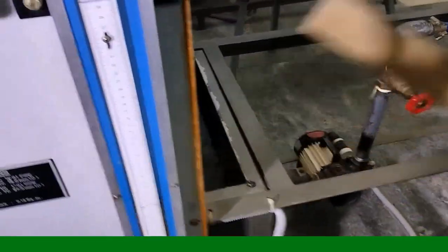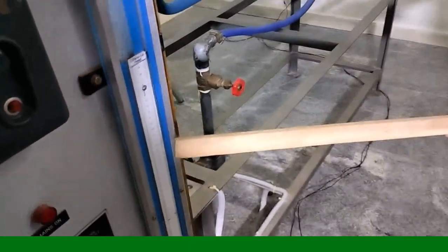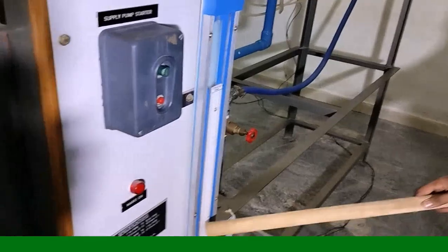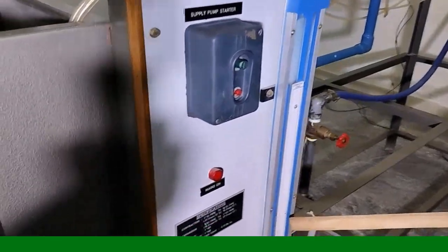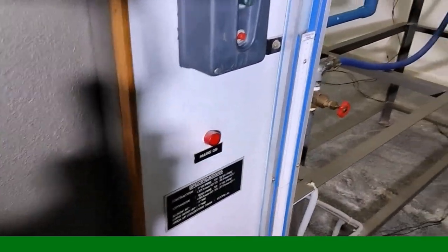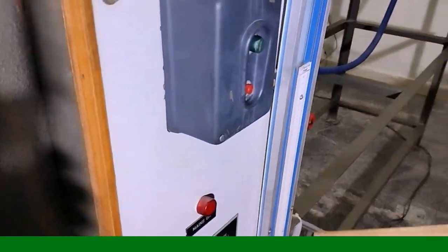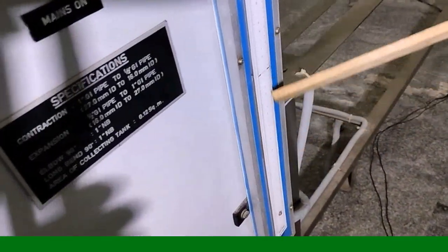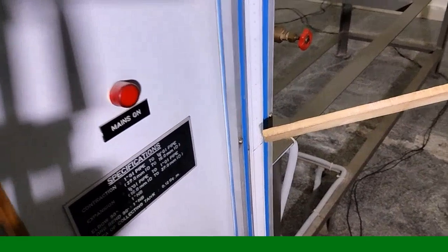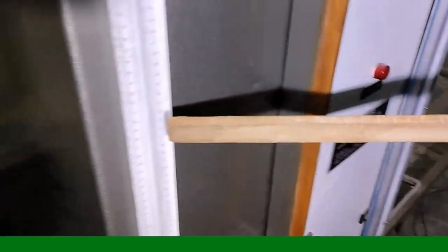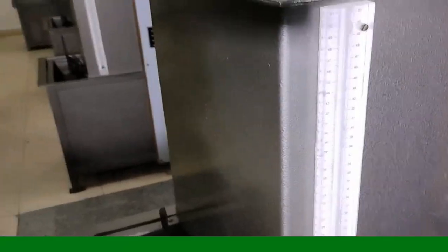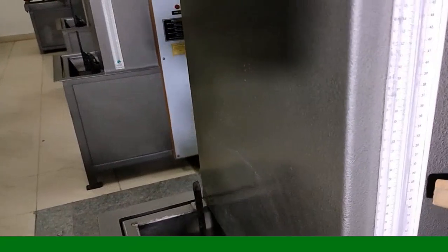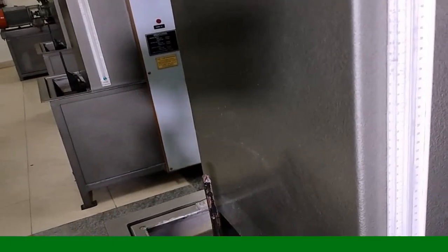This U-tube manometer gives the pressure difference between the larger diameter and the smaller diameter pipe in the sudden contraction. Later, for a known amount of water rise, we collect the height from this tank. This tank we call the measuring tank, also the collecting tank, but since it has a scale, we call it the measuring tank.